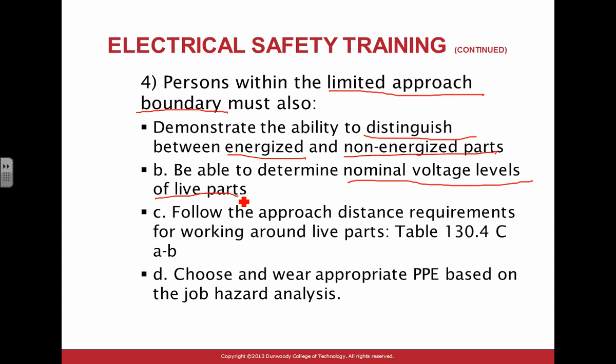I always say, guys, it's a crime going to troubleshoot a piece of equipment when you don't know what voltage levels we use in the US. You're measuring and you find 220, 222, and you don't know that 240 is a system that we use. So you need to have an idea. For example, 208/120 is a nominal voltage system that we use in the US. 480/277 three-phase system. These are the nominal voltages. You're looking at something close to these voltages, 240, 120.